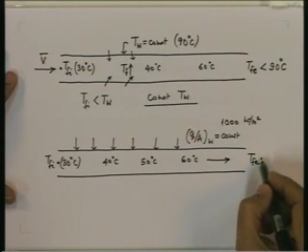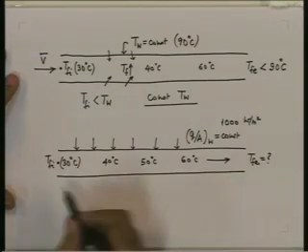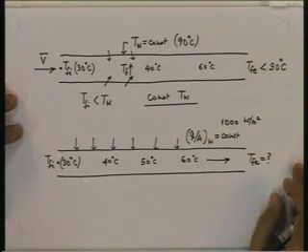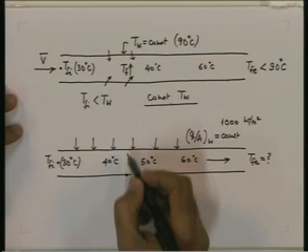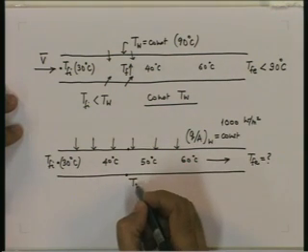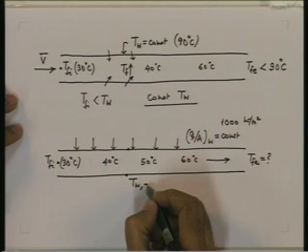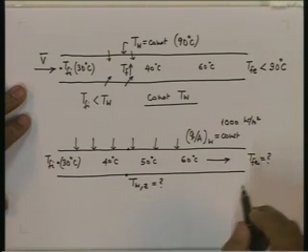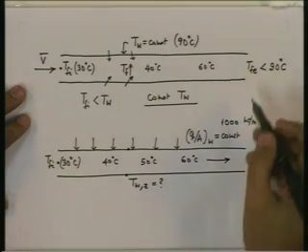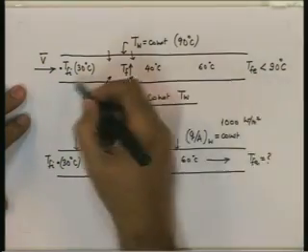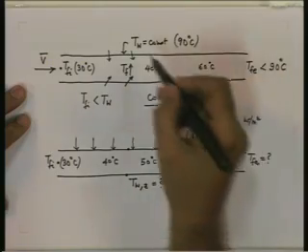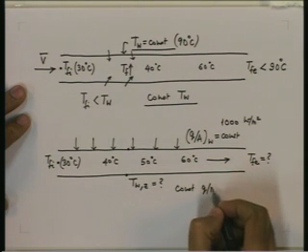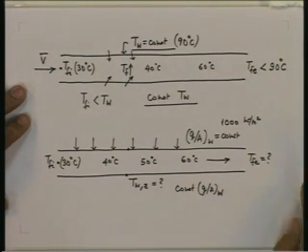What is the exit temperature? There is no limit. It will have to be calculated based on the area, the amount of heat flow. The wall temperature will also need to be calculated. It will vary along Z. We will have to determine what it is. Exit temperature will also have to be determined. Here, the temperature will also have to be determined along the fluid flow and the exit temperature, but the wall heat flux is maintained. This is the constant wall heat flux situation.